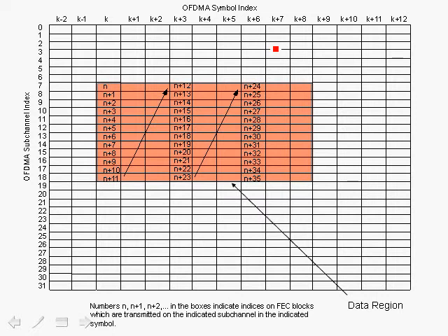Now that we have introduced the concept of subchannels, in which subchannels represent multiple carriers that are obtained through permutation, in the case of 802.16a OFDMA, we have 32 subchannels, and each subchannel contains 48 carriers. So let's look at the grid over here, in which the arrangement is in terms of the subchannels. So we have 32 possible subchannels.